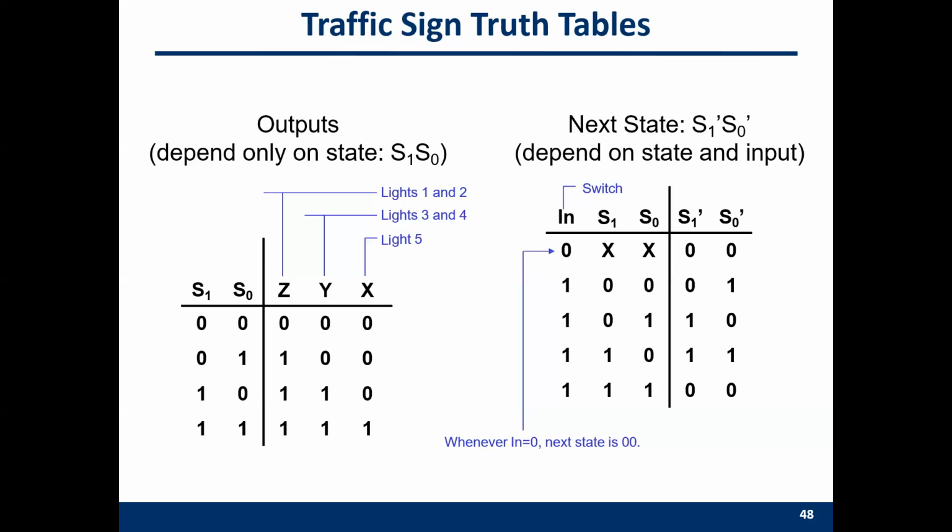We have 5 lines. So in order to control these 5 lines, we need a 3 bit output. 2 to the power of 3 is 8, and 8 is larger than 5, so this is enough. If we only had 2 bits here, we could only control 4 lines.